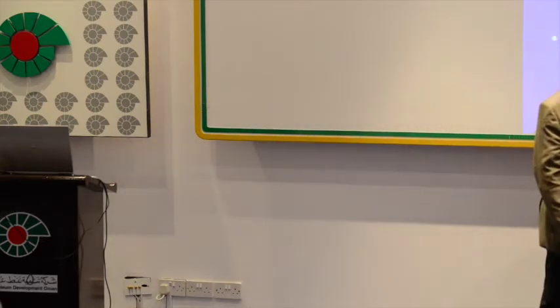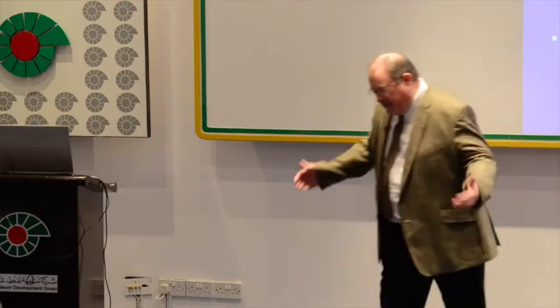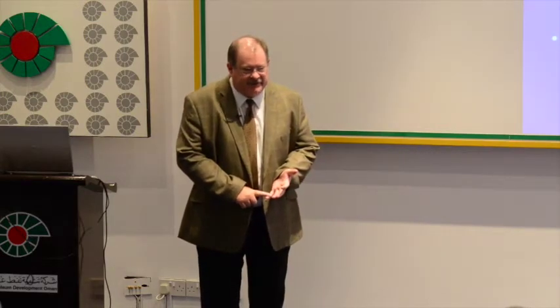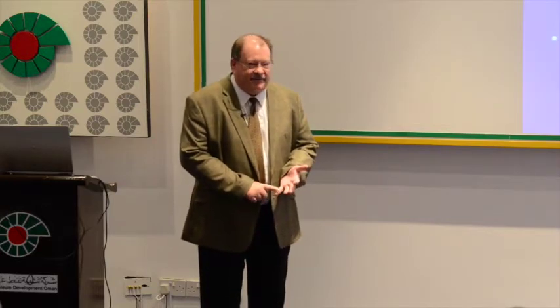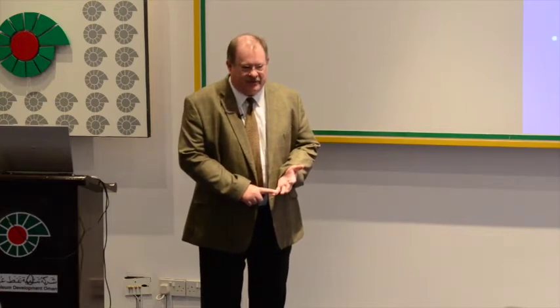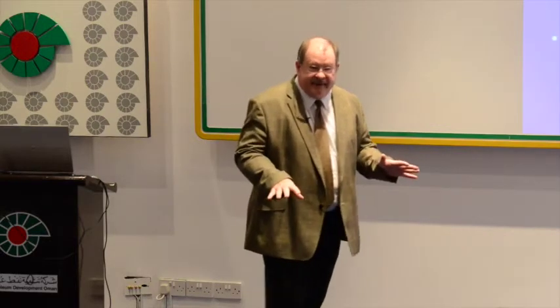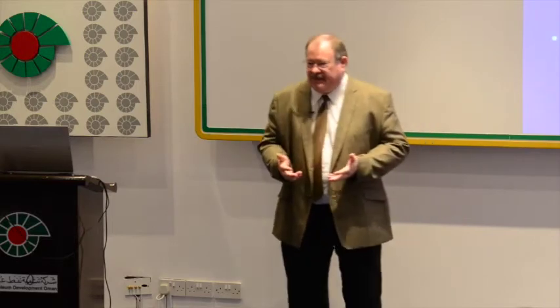And here's a word which I despise, but I put it in here anyway: frackability. There's a lot of jargon that has come into the unconventional literature which just drives me nuts. Words like brittleness index, right? You guys have seen that? Brittleness is a failure mode, a geomechanical failure mode as a response to stress. It's not an intrinsic rock property. So why are we doing log calculations to tell me what the brittleness index is? There are a lot of things like that, and we have to be careful what we do. But frackability is a word that I very casually use to just mean, can I complete this rock effectively?